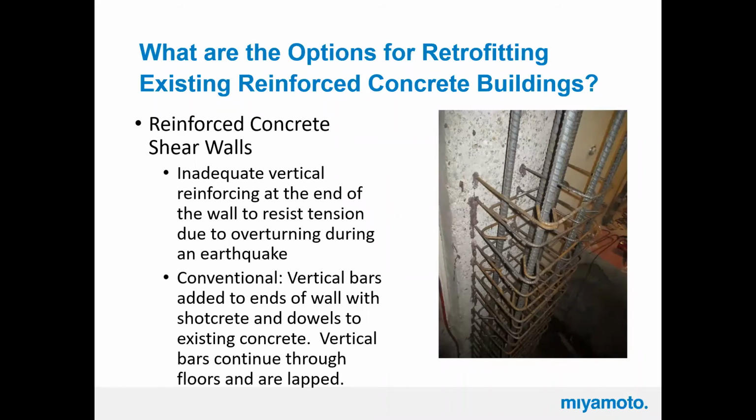Again, another picture of a confined end of a concrete shear wall. Looks like we're increasing the shear wall. We're adding a boundary element to the end of the shear wall. So again, it's just adding concrete, and it's adding a lot of reinforcing and a lot of ties that create ductility. So pretty interesting. We'll be doing a lot of this after the next good size earthquake, all of it.